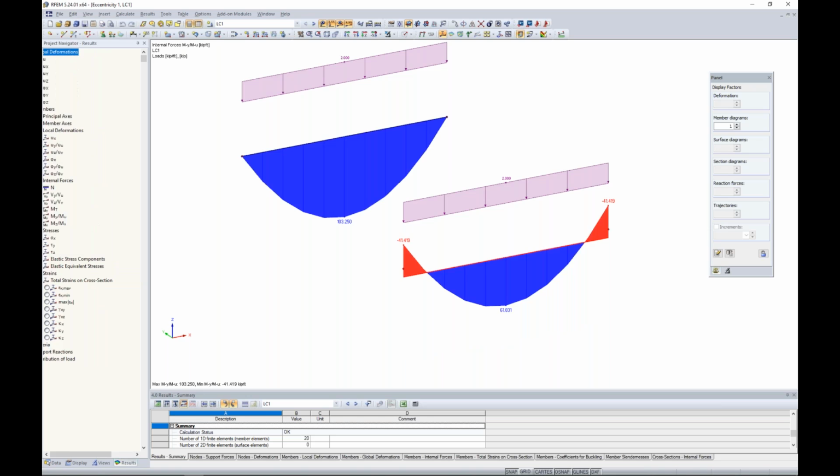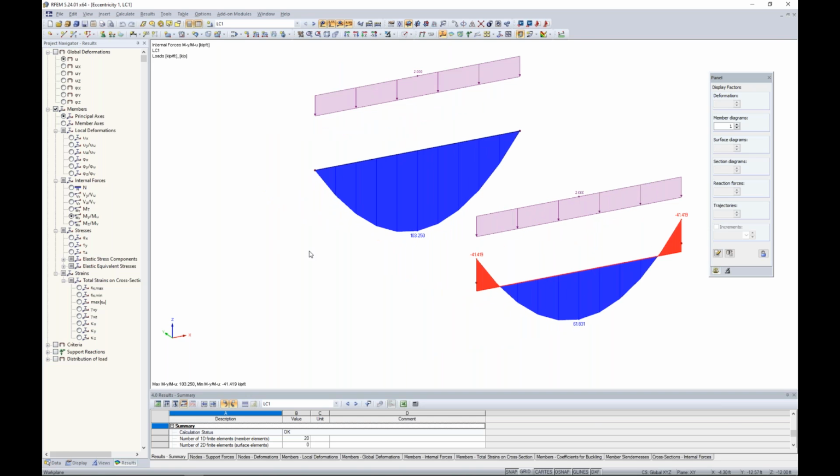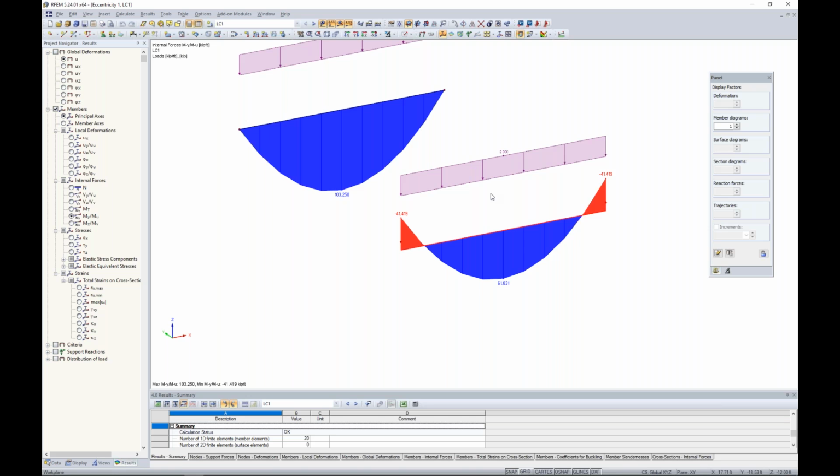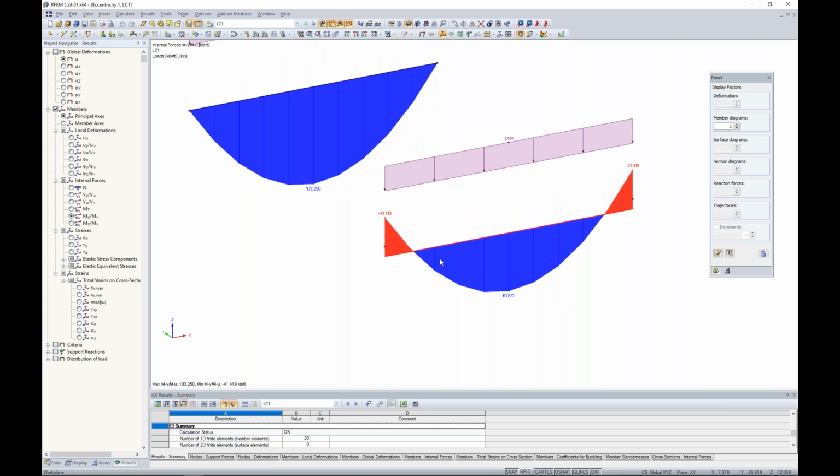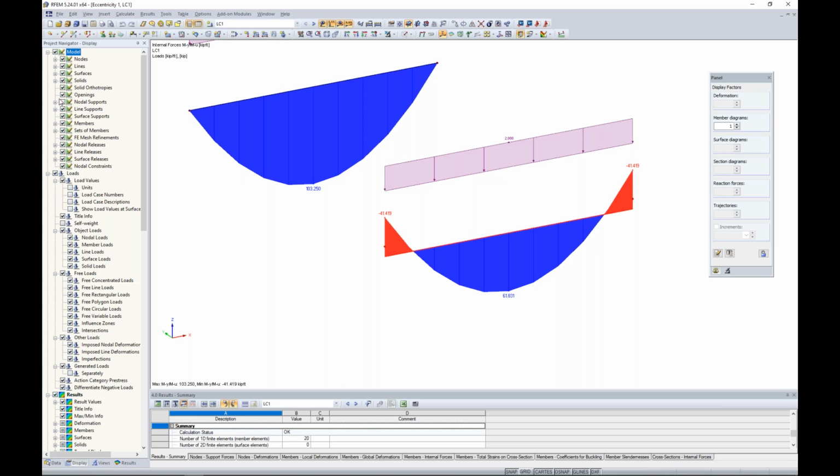We'll immediately start off with the moment diagram. For a simply supported beam, we take a look at our first example here. This is exactly as we'd expect for our moment diagram, peak moment right here at the center. But as we transition into those nodal supports, which are a pin-roller type situation, we expect no moment. Well, by introducing this eccentricity to drop the top of steel down to where our nodal support is, we now have a negative bending moment here due to those rigid elements at the end. Our peak moment here in the center is almost half of what we're seeing with our original beam element.